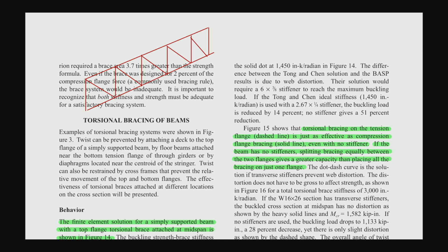The point is that the roof truss is prone badly to instability, and in the practice of roof truss design, generally people will say that, okay, it is well braced. All right, well braced. Okay, you can say so, but who takes care of the brace design, brace analysis, second order analysis also? I don't think many people really understand how this is taken care of. So the roof truss design, generally I think it is not done in the right way.